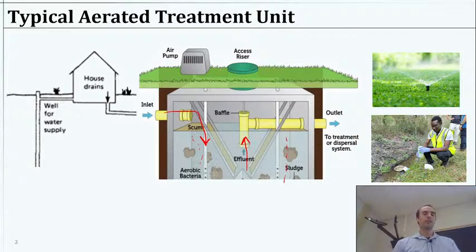I've seen cases where you have this little air pocket, or air vent system. We'll see a couple of photos. If you end up getting, let's say, an ant hill growing around it, it could just block the incoming air, and then you're not getting any air into the tank. And it sounds like it's running, the motor's humming along, but you're not getting the treatment. It becomes similar to a septic treatment, maybe with a tiny bit of air, and that's going to be gross when it comes out. It's going to be stinky, all of that. So that's just not a good system when it's malfunctioning.